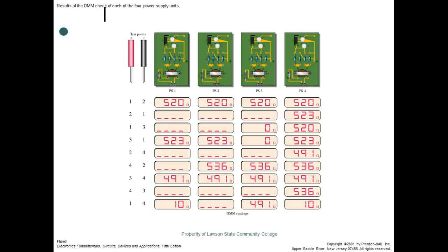By the way, ohm meter in the circuit. What should be the power when you put an ohm meter in the circuit? Should be off. Everybody understand that? So we got 2 meters we measure across with. And that's our ohm meter, and that's our voltmeter. Voltmeter, we make our measurements usually with power on, unless we check it to see if power's off.